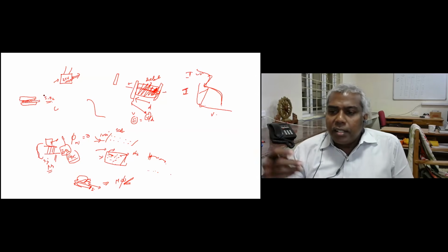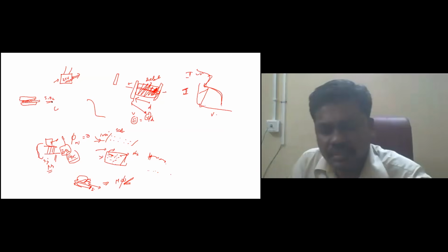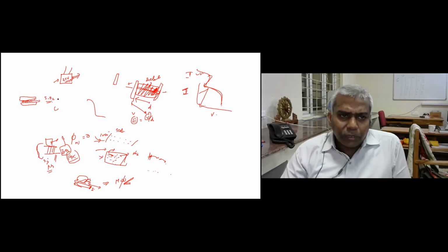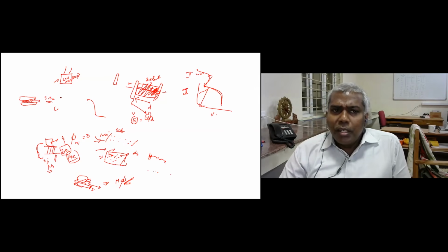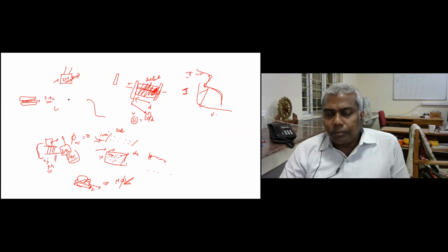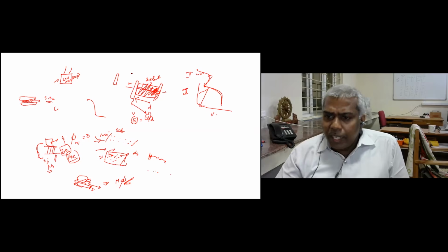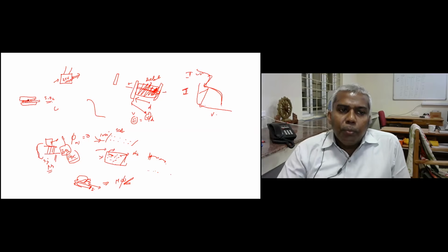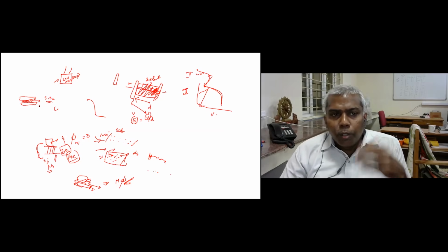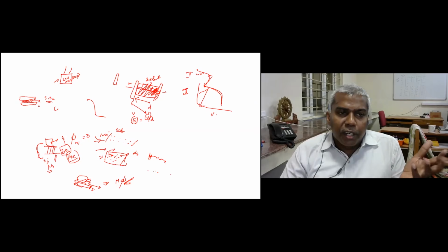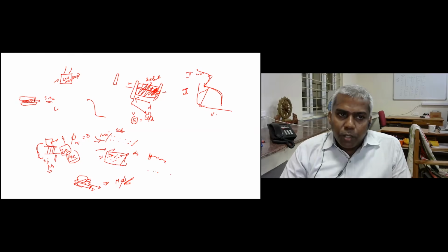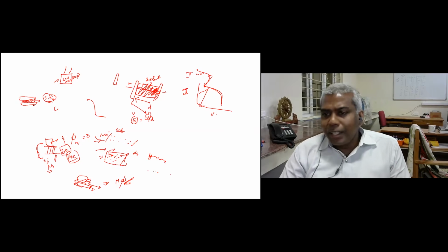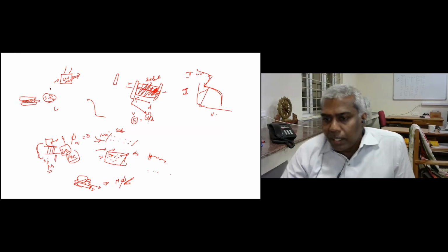But now miniaturization is to be done. If you want to coat MOS, the silicon oxide has to be a few nanometers or a few tens of nanometers, maybe 10 nanometer, 20 nanometer. Now, one capacitor I've shown was 90 nanometer thick. So when you want to make more components in less area, that's what we call miniaturization. This thickness has to be reduced. So when you want to use the same material, silicon dioxide, it will be leaky. That cannot be controlled because that's the nature of silicon dioxide.